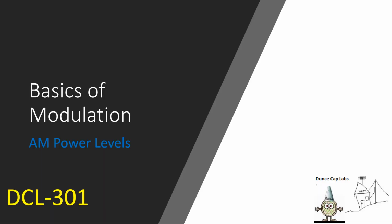The next thing we must talk about is power levels, because clearly in AM, the power of the CW carrier isn't steady. It might have a reference level, but when you start speaking, the power level of the carrier is all over the place, from almost 0 watts to twice the power, or maybe even more, of the original carrier. So let's look at the math.